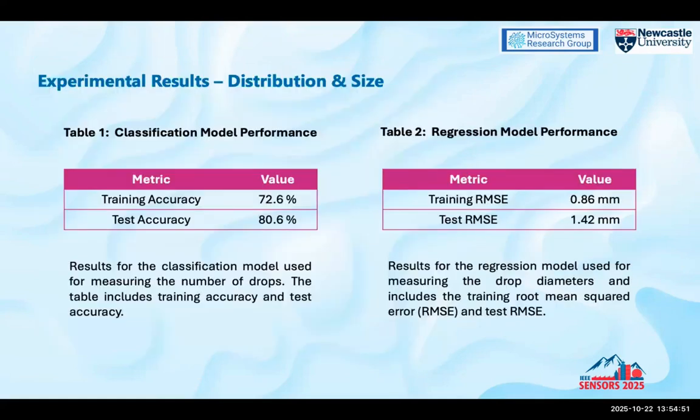So these were the initial results. What you have to remember is we're not looking for perfection here. We're looking for an indication of how big the raindrop is to feed into an algorithm. This is not a scientific piece of data that will be used for meteorological purposes. This is literally just to say that during that storm, the average drop size was what it was, and we can then feed that into the algorithm along with the quantity of rainfall. Also, you'll see later we're going to add ultrasonic wind sensors to the gauge, which will give us the wind speed at the time.